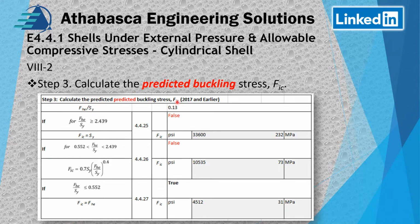basically I have a ratio here, and we do this. There's 3 steps. So this is all conditions. So first thing I always do is set up the ratio of that elastic buckling over Y, and you get a ratio. And then basically you can sort of plug that into here and then get a conditional statement. So it says false. I can't use this equation to determine my predicted buckling stress. So I got to continue.